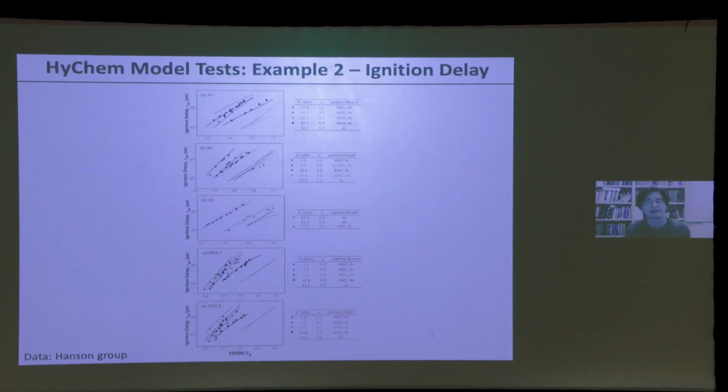The next question is, do some shock tube ignition validation. Turns out that most of the species measurements were made at 12 bar. You're then going to ask the question, can the model be extrapolated to higher pressure and to a wider temperature range? The answer is definitely yes. Remember, those Greek letter parameters are not dependent on temperature, not dependent on pressure either. So as we expect, when you derive the model parameters at around 12 bar and apply them to 50 and 30 bar high pressure, you predict things very well.